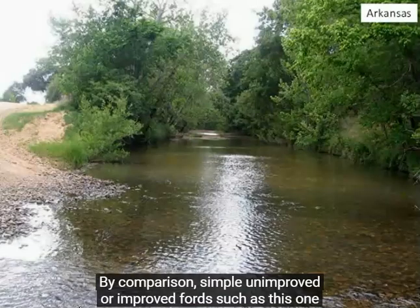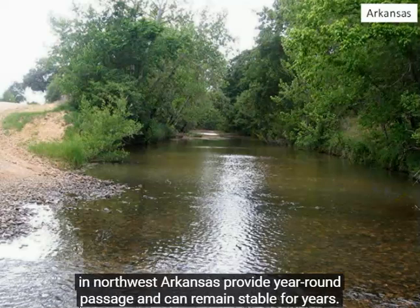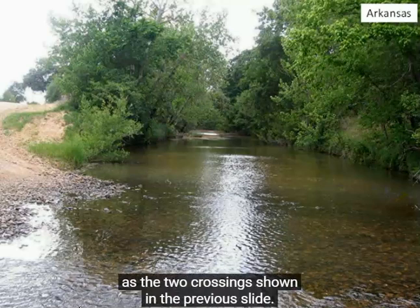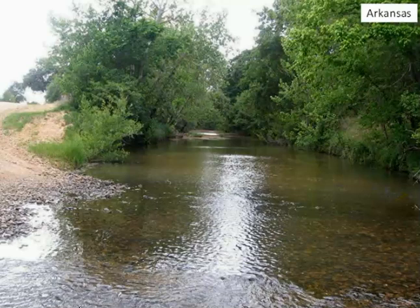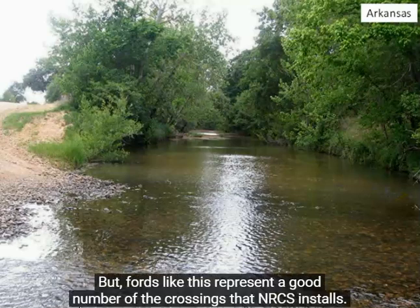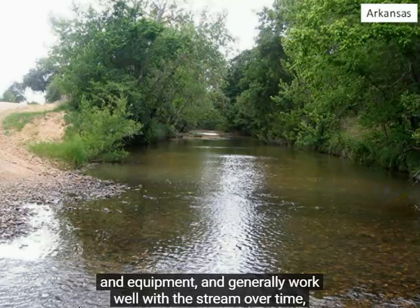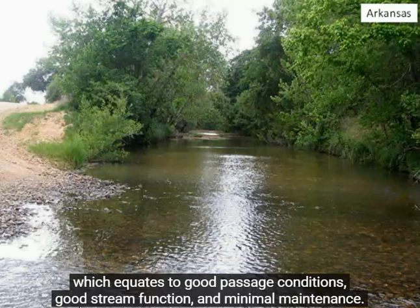By comparison, simple, unimproved, or improved fords, such as this one in northwest Arkansas, provide year-round passage and can remain stable for years. Granted, they won't support the same equipment load as the two crossings shown in the previous slide. But fords like this represent a good number of the crossings that NRCS installs. Simple fords offer a good mix of construction ease, stability, safety for livestock and equipment, and generally work well with the stream over time. All of this equates to good passage conditions, good stream function, and minimal maintenance.